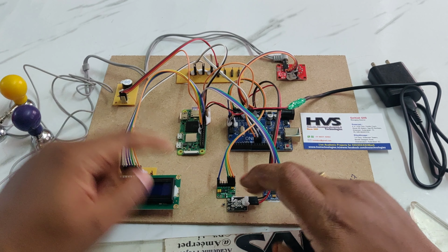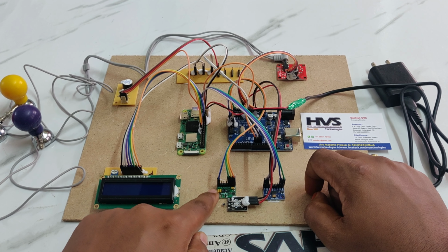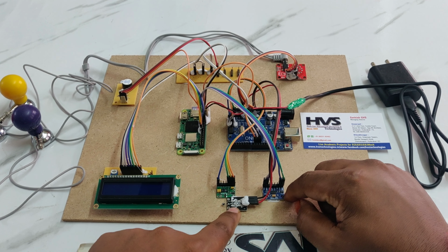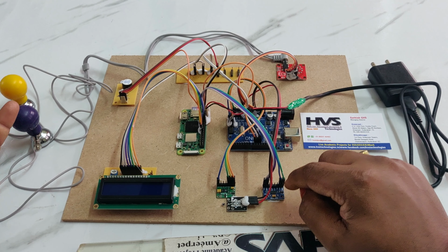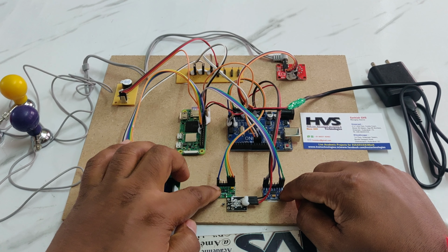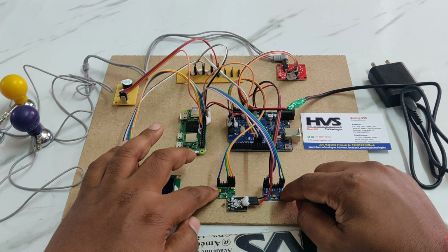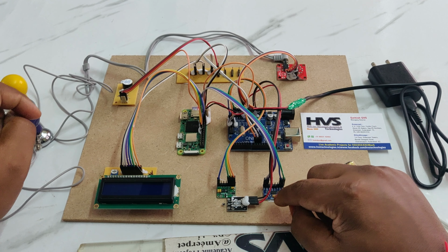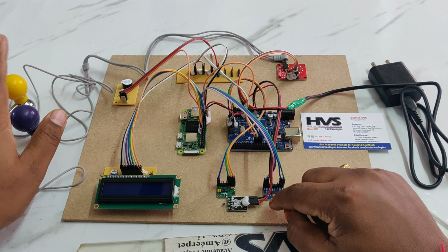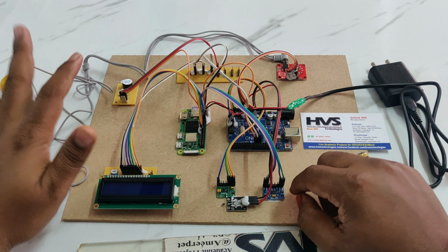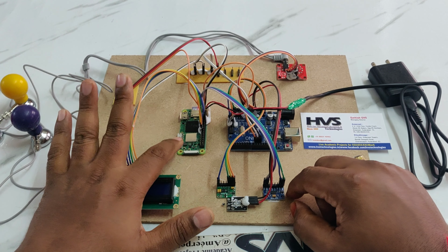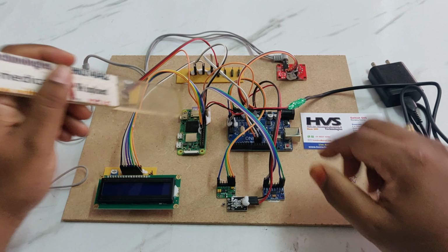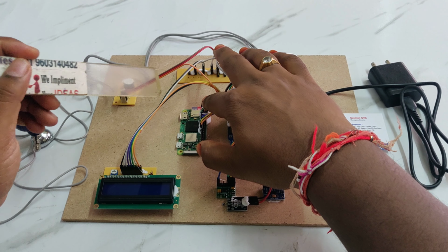And we have interfaced the MAX30100 heart rate sensor, a thermistor temperature sensor, and a MEMS ADXL345 for fall detection. The fall detection is for that purpose, and heart rate and SpO2 are obtained from the MAX30100, along with the thermistor temperature. So in total we are getting 4 health parameters including the ECG, plus fall detection. These sensors are continuously monitored by a Raspberry Pi Zero 2W, and here we have inserted the memory card, which is a 32 GB Ultra Class 10 memory card.